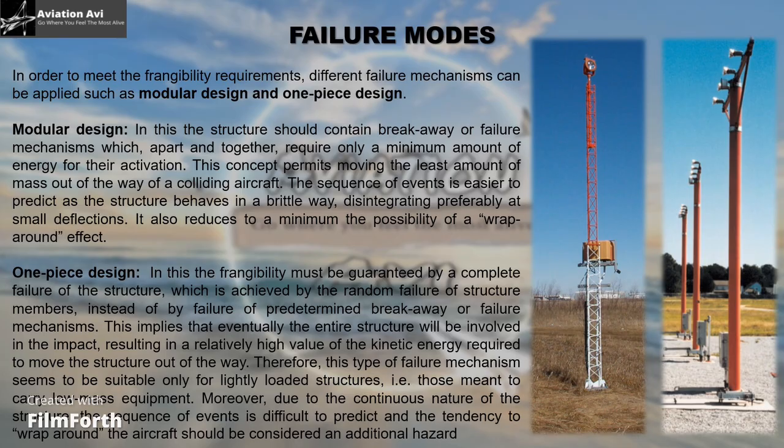for its activation. The concept permits moving the least amount of mass out of the way of the colliding aircraft. The sequence of events is easier to predict, as the structure behaves in a brittle way, disintegrating preferably at small deflections. It also reduces to a minimum the possibility of a wrap-around effect.